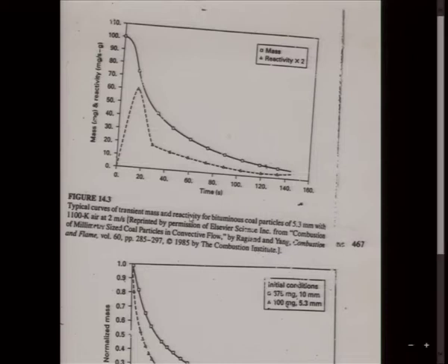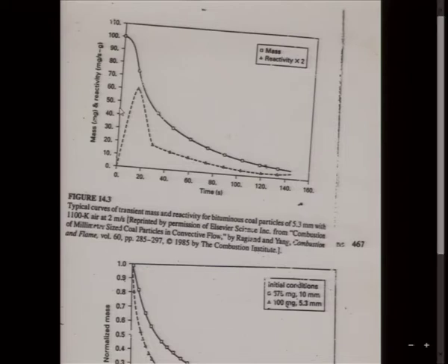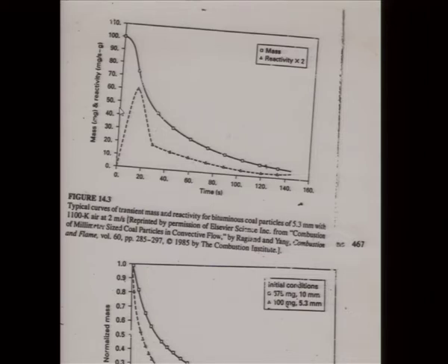So here, coming back to this plot, pyrolysis is roughly ending here, from what we can see from the change of slope. So if you go up like this, you will know that at the end of pyrolysis, the mass is actually 45%, isn't it? The initial mass is 100 mg, 100 mg has become 45 mg, correct? So it has lost that much mass because the volatile matter escaped and burnt in a flame.